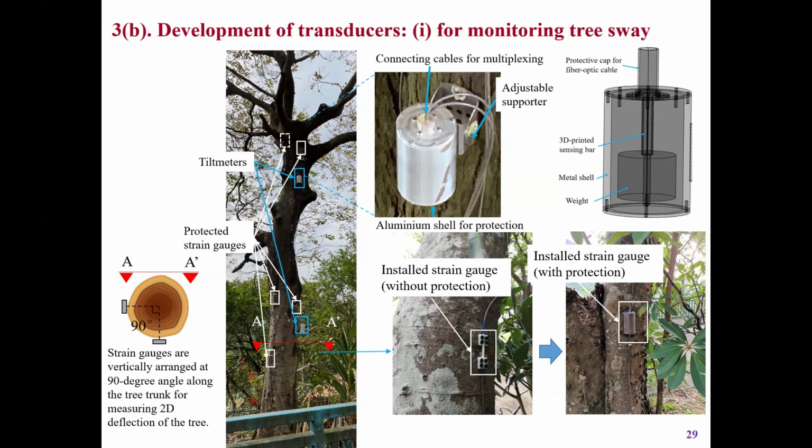We tried two sensors. One is a strain gauge. You can see the strain gauge here. It's not metal, because the Young's modulus of the tree is not really strong, so we cannot use metal as a strain gauge. So we use some high strength plastic, then put a tiny FBG, fiber Bragg grating, on here. Then use a nail to fix this strain gauge on the trees, because when the trees are subject to wind, we can measure the strain, tension or compression.